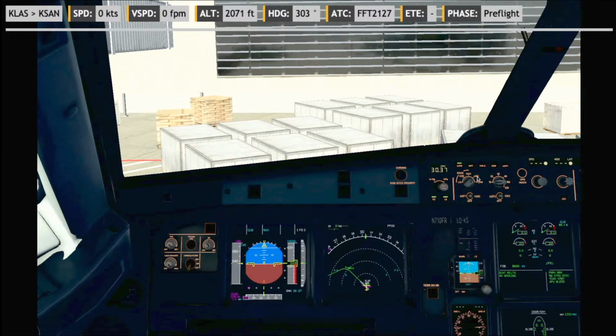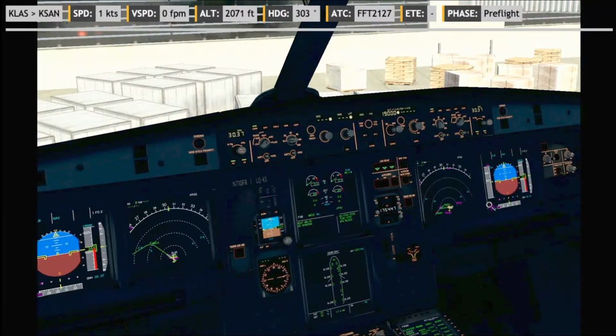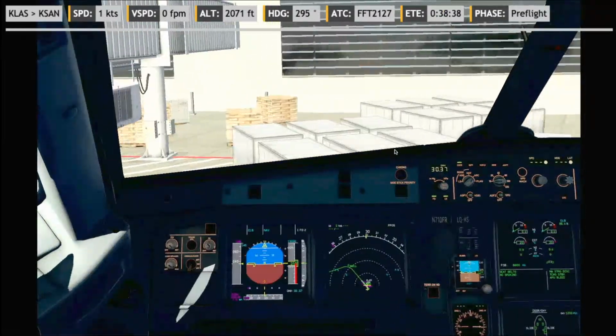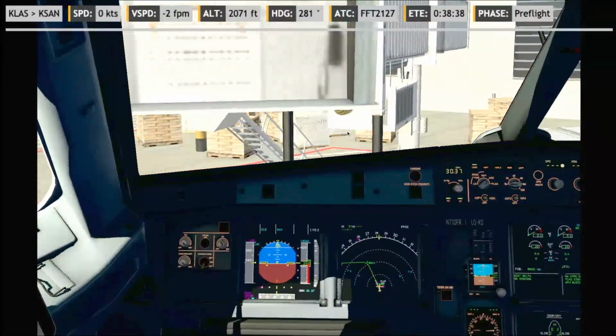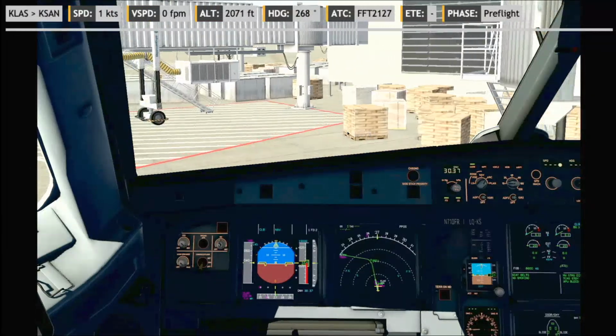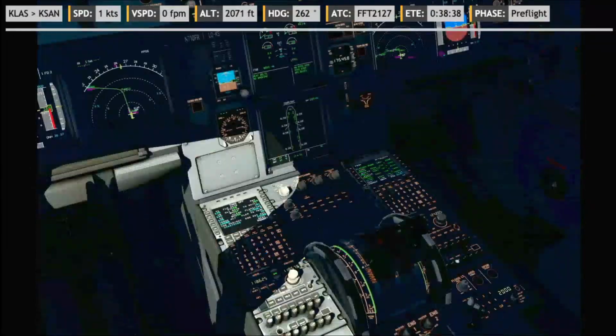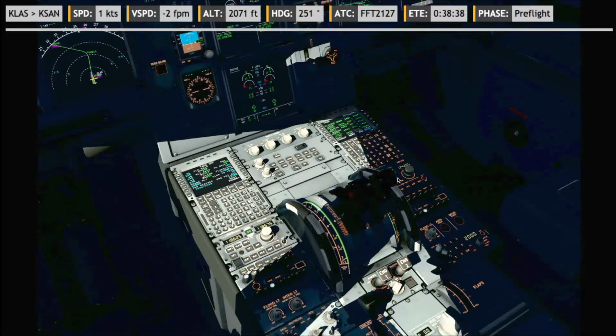So connected and bypass pin inserted. Release parking brake. Alright, we will release our parking brake. Parking brake released. Starting pushback, and you may start engines. Alright, starting number 2, then number 1. Engine start, selector, ignition start, starting number 2.